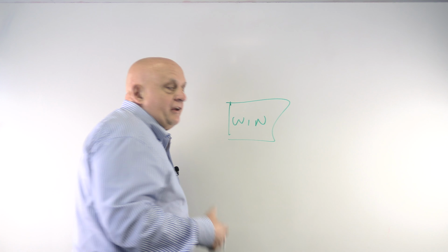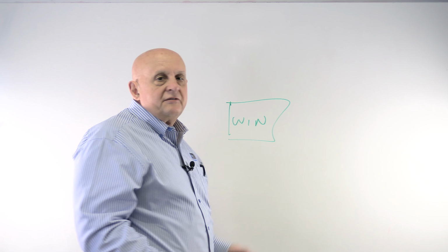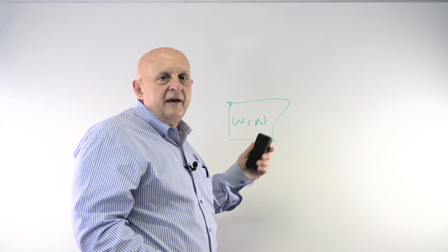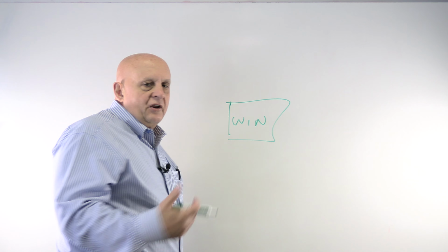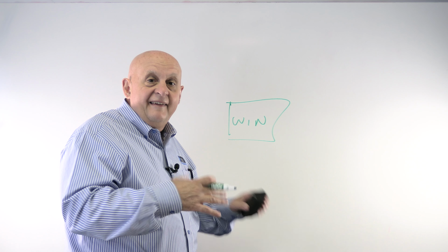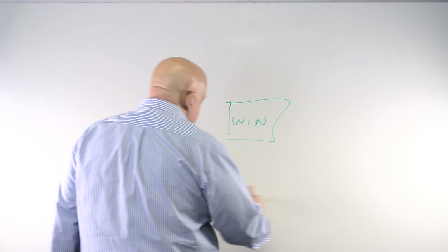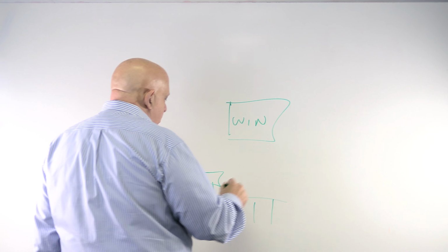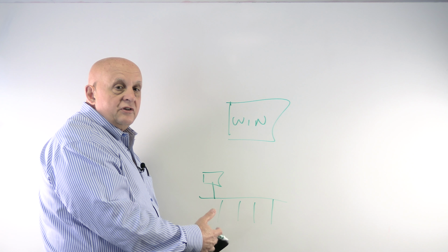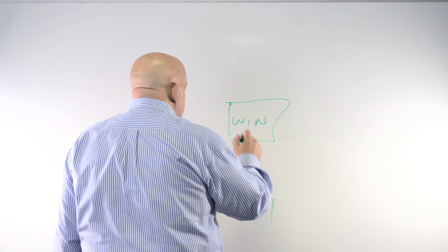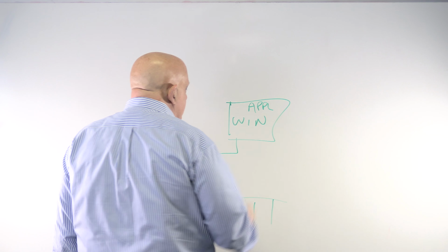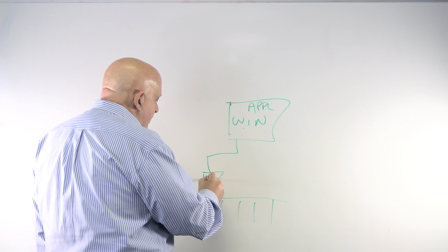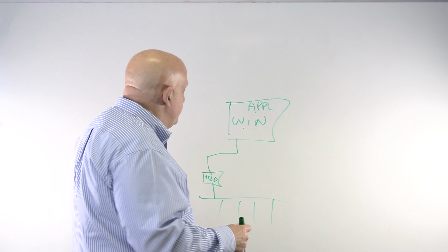So, the thing about that is, there are people all over the world that know how to break into Windows. That's all they're doing, figuring out how to hack into Windows computers. Not a good idea, I think, to put them directly in the control system. The control system should be separate from any Windows PCs that are needed to operate things in the control system. The reason for that is because these applications then can be controlled. So if somebody hacks into this Windows computer, the ICS Defender can stop them from doing things that they don't normally do.